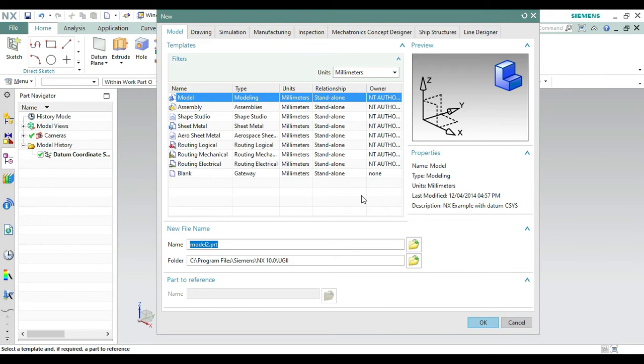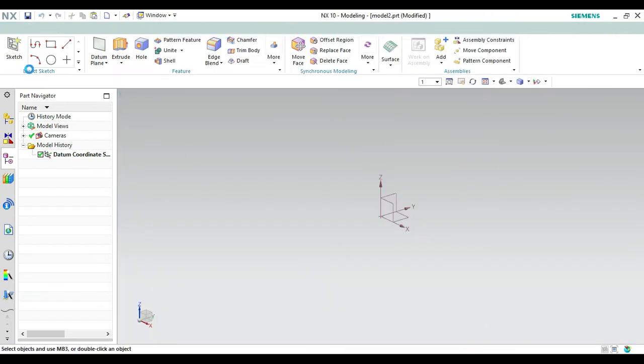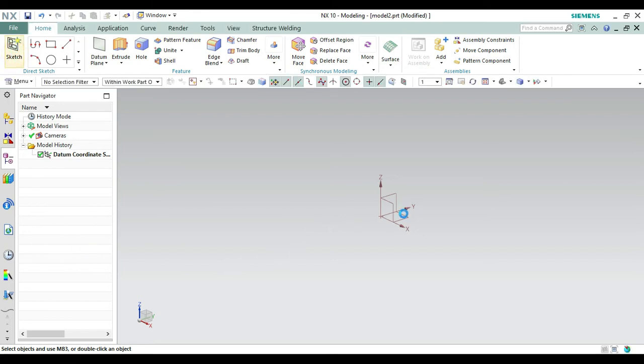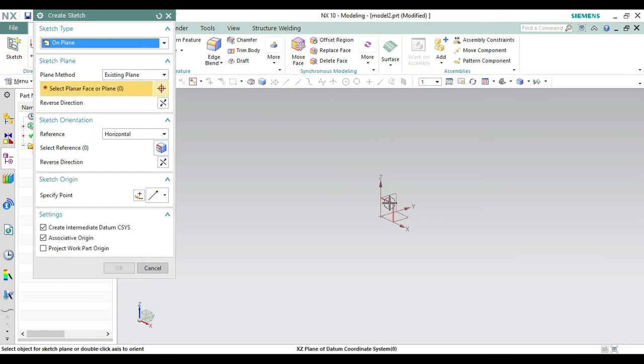Part of the assembly, and that is the king, the main king of the chess. So from here, first click on this model and make it okay. Now again, similarly, we have to select the sketch on which plane we want to work. So from here, go to sketch, then select this front plane, XY plane, or YZ, anyone you can select. Okay, from here and make it okay.